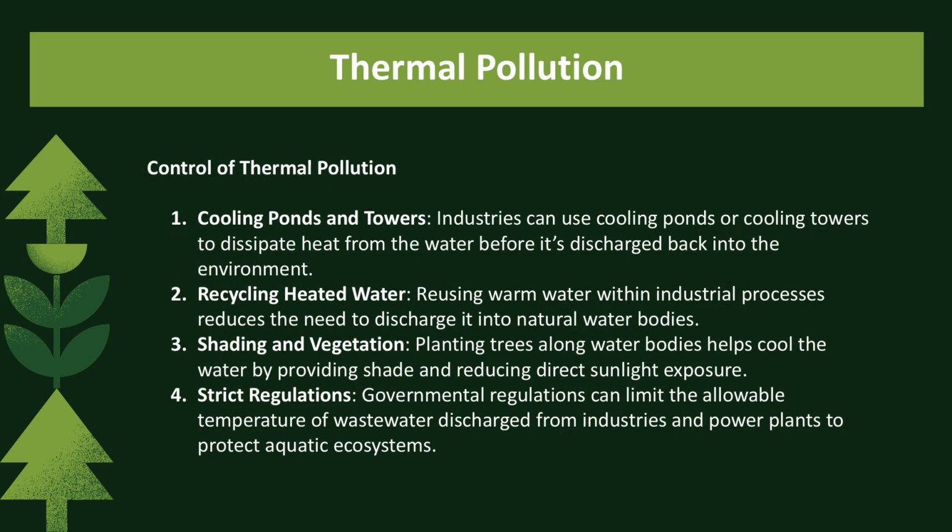To control thermal pollution, several methods are employed. Cooling ponds and towers help dissipate heat before water discharge. Industries can recycle heated water within their processes. Natural solutions like planting trees provide shade for water bodies, while regulations limit the temperature of discharged water.